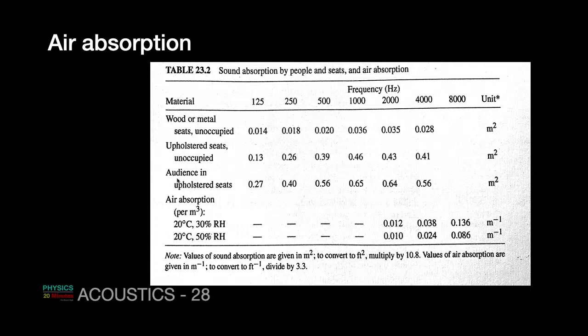Upholstered seats with audience: if people are sitting, then it will have even different absorption. So absorptions are going to be different. Air absorption, finally, as I said, at lower frequencies is not very important, but at higher frequencies it's significant, and that has to be taken care of in the calculations. So all these things will come into calculation. So please be aware.